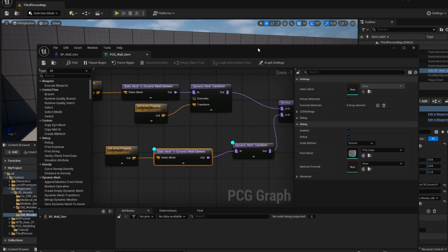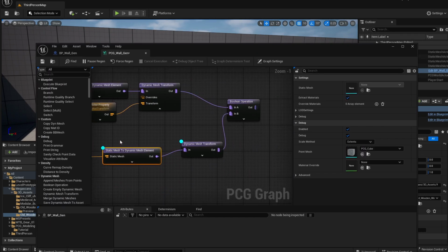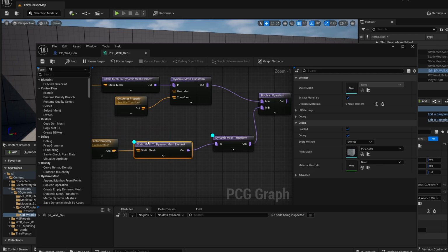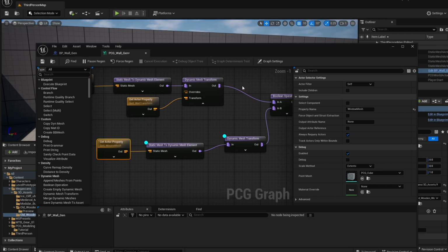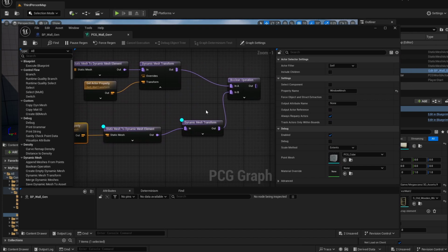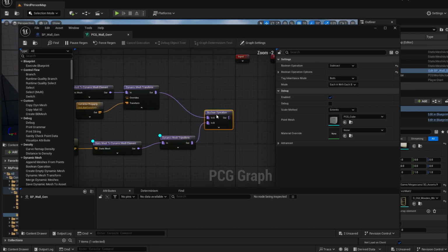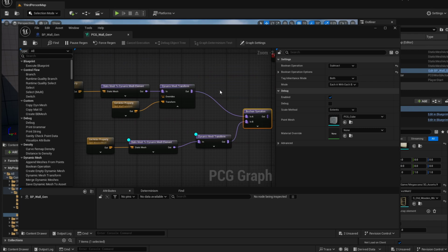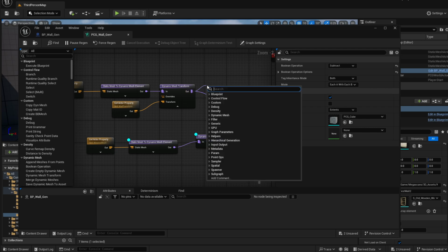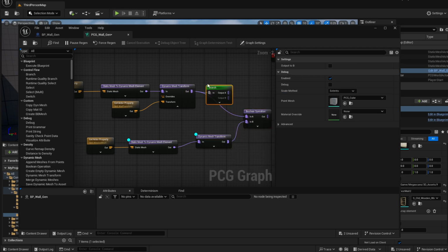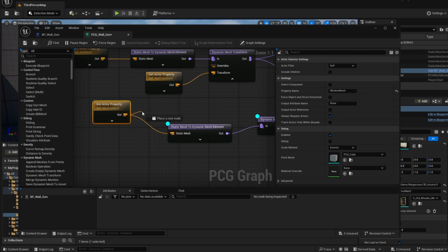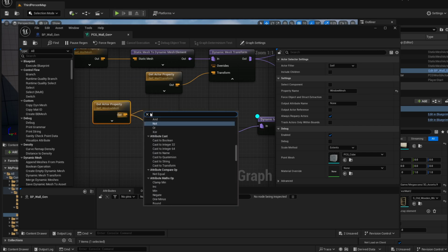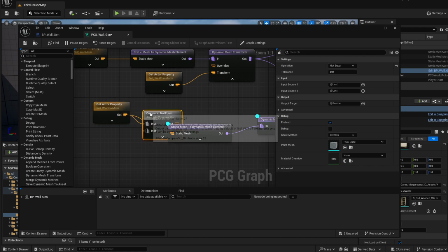So in order not to have this problem, if you don't have a mesh connected into your window mesh property, you don't want the whole script for this wall generation to stop working. You know how to fix this by the save path example before. Do a branch here. Let's compare this window mesh property with not equal.